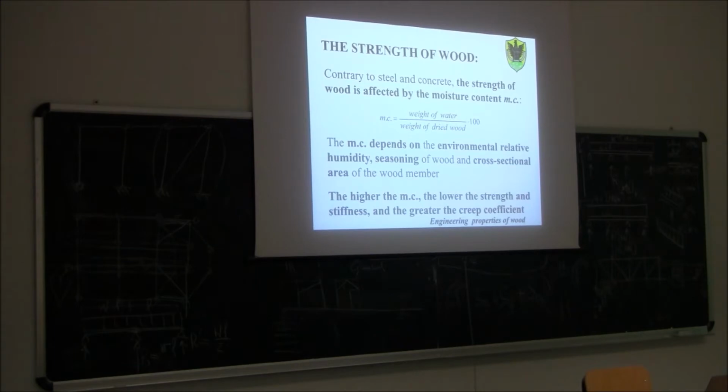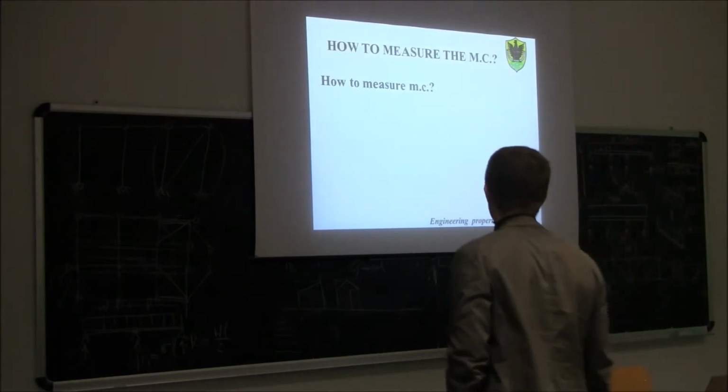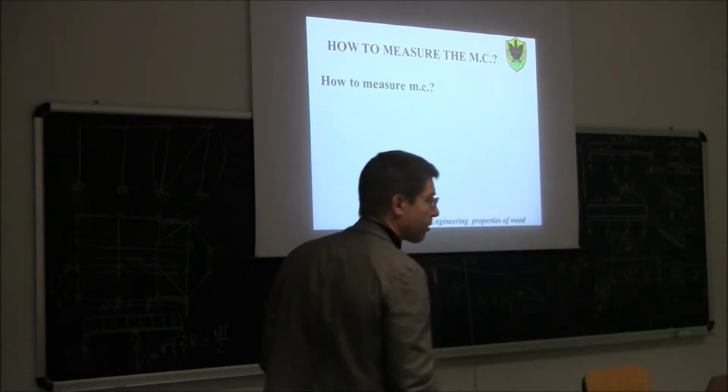And as you can see, the higher the moisture content, the higher the creep coefficient, so the higher the deflection. So this is another good reason why we have to keep the moisture content not too high, in order to reduce the deflection of the beam and so the creep coefficient. First of all, how do we measure moisture content?